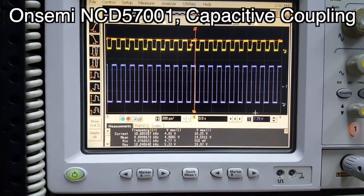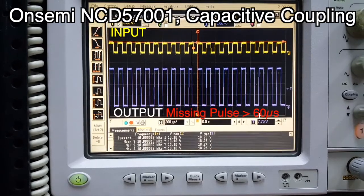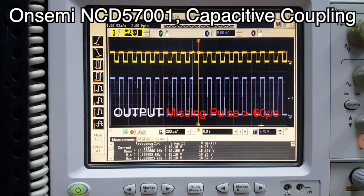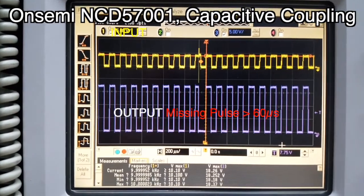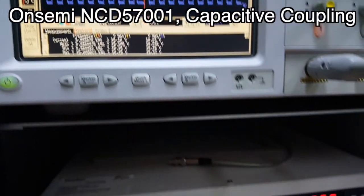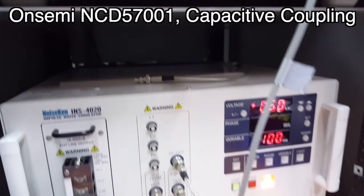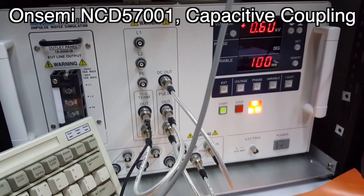The first gate driver we're going to test is onsemi's NCD57001, which uses capacitive coupling. It is a 16-pin gate driver with a DSAT protection feature. The onsemi gate driver is failing, as there are missing output pulses when 600 volts periodic impulse noise is introduced on the surface of the gate driver's package.